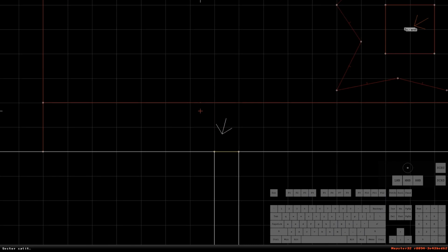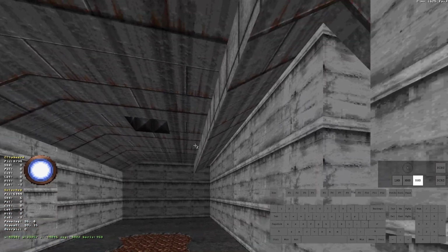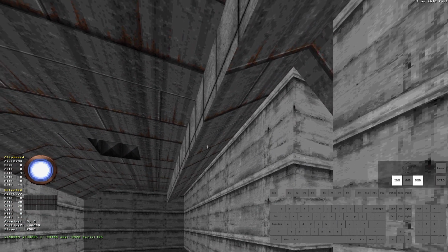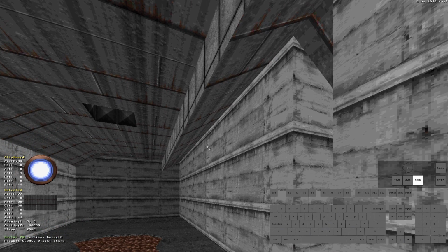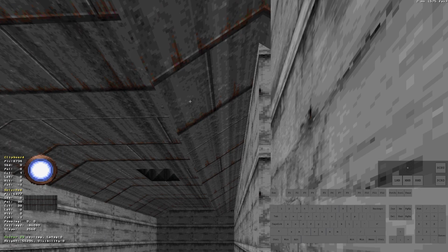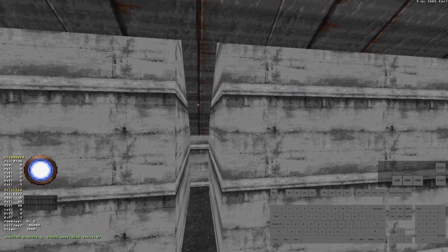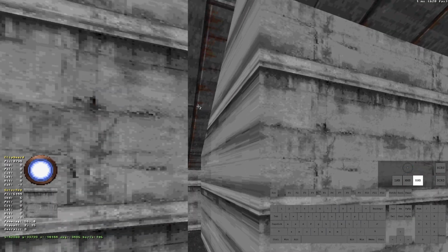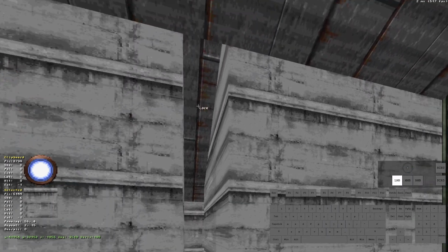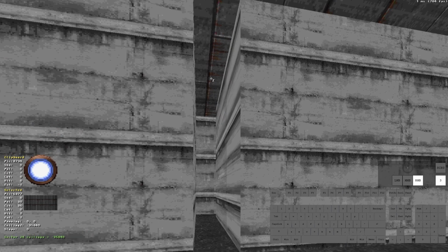As soon as we divide the tunnel sector and the vent sector, the slope on the tunnel changes. That's because creating a new sector or adding new walls usually changes the first wall of the sectors. We fix this by pressing Alt+F to set the first wall of this sector again. Now our vent sector has a slope that we don't need. We can make the ceiling turn to its standard property by pressing slash. This will turn the slope to 0, completely flat.